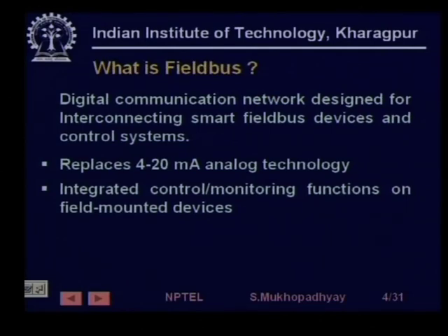Previously, the field mounted devices were mostly not able to perform computation. So, in that sense they were not intelligent. They were mainly devices which handle the power and actually create the physical effect, maybe in terms of flow. For example, a valve positioner will actually drive the valve shaft, or it can be a heater, right. So, previously the field devices were unintelligent, and therefore all the control and monitoring activities had to be situated at a host computer.